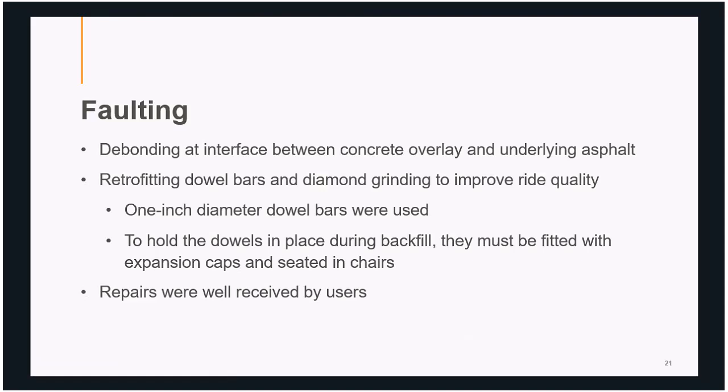So 1-inch diameter dowel bars were used in this case. And in order to hold the dowels in place during backfill, they were fitted with expansion caps and also seated in chairs. For these projects, the repairs were well received by the users.